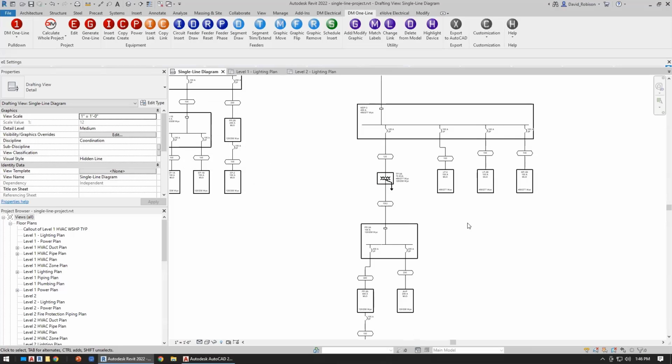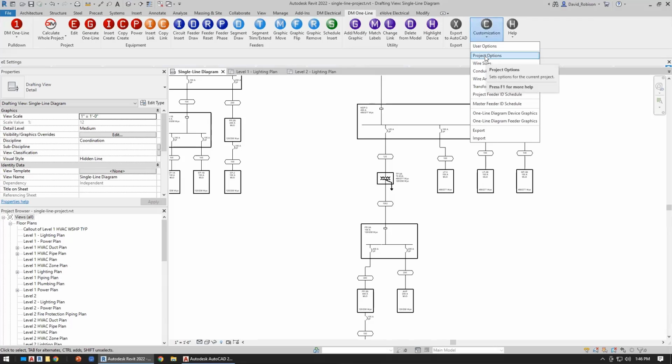If those project settings are chosen in our template file, will they carry through for all projects? They will. So this is a standard Design Master customization rules apply. So if you go to your project, a template, and you set project options in the template, it'll carry through to future projects. You can also import and export your project options from a project. So get one set, export it, and then import it to your other. So there's two ways to get your customization transferred between projects, either set it up in a template or use our export and import.